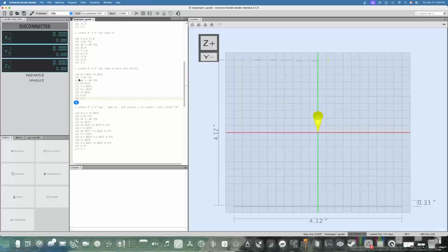The problem with R is if you have a GRBL machine that's only 8-bit, Grbl themselves tell you don't use R at all. And if you get into a more complex shape, like a helix bore cycle or a threading cycle, if you use R, odds are good the machine's going to get lost and take off, and now you've broken the thread tool or the end mill you're helix boring with. So for simple corners, like on this one box contour, that's okay.